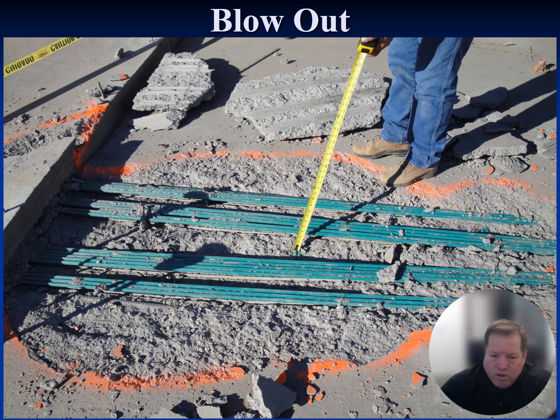The tendons are the strongest when they're stressed, and then they start relaxing and drop their force. The concrete is at its weakest, and then each hour, day, month, the concrete grows stronger. So the tendons get weaker, let's say, the concrete gets stronger. So if it holds at stressing, most likely 99.9% of the time it's going to be fine moving forward. But the great thing about PT is you don't have to wait to see if it's going to work. Once you stress it, if it has a problem or there's an overbalance condition, we can see here, it's going to let you know about it.